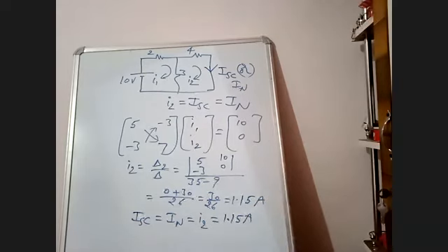Okay, now we'll determine Rn, the Norton resistance. Note down: Rn and RTH are same. Why? While determining RTH, we shorted all voltage sources and opened all current sources. Similarly, while determining Rn also, we will short all voltage sources and open all current sources.